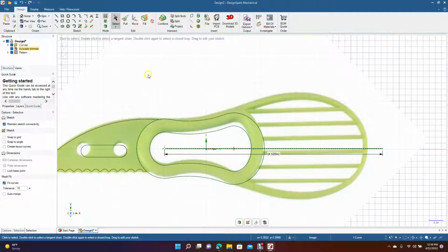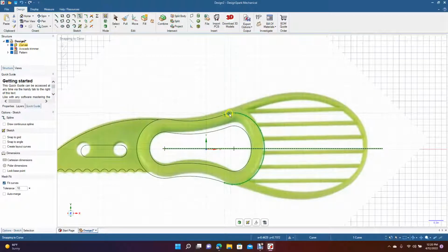Okay, so what we want to do here is create this shape here. So I think what I'm going to do to create that is use the spline tool. This is going to be the most accurate. We're going to just click and kind of drag with our mouse, or if you have a keypad like I have, just go ahead and click and drag. Now for some reason it didn't draw this bottom part, so let's undo that. Go right to there, let's select. Let's make sure this has the mirror on. So right mouse click. Okay, there we go. We didn't have set as mirror on.